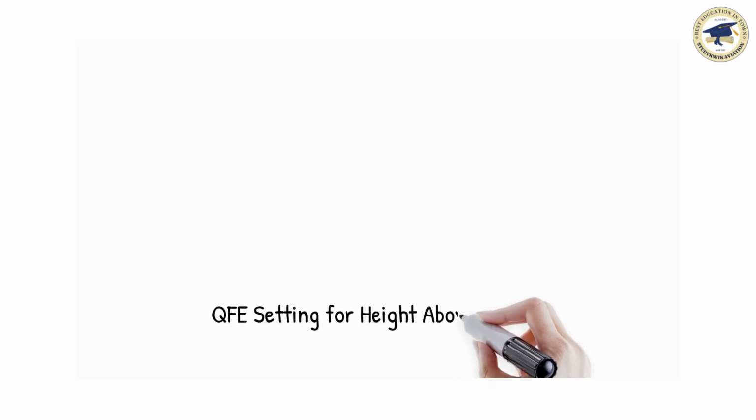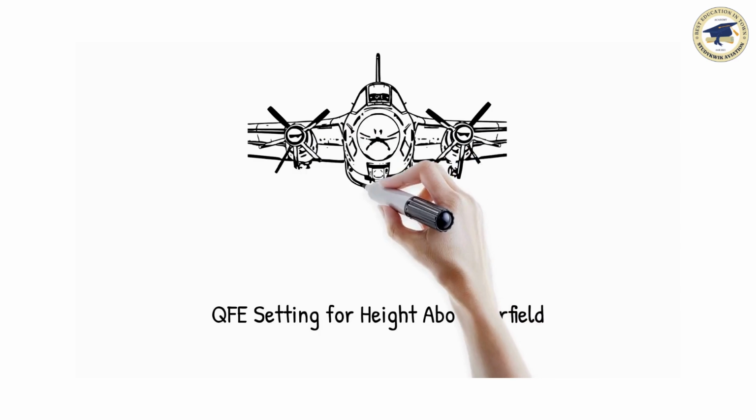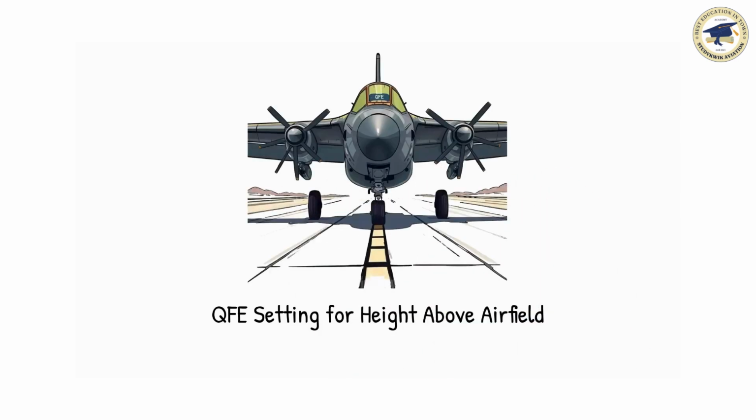QFE makes your altimeter read 0 on the runway, showing your height above that airfield. Used mainly in military or aerobatic flights. Less common commercially since it requires resetting at each airfield.